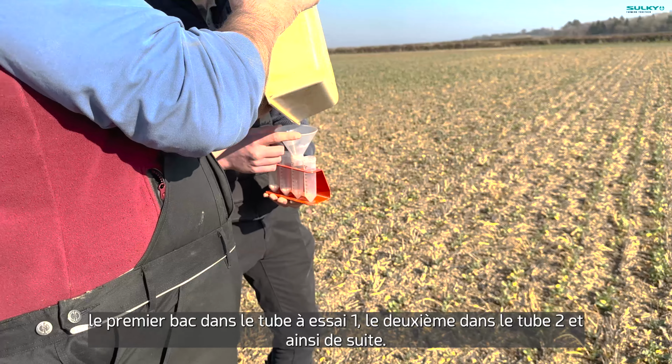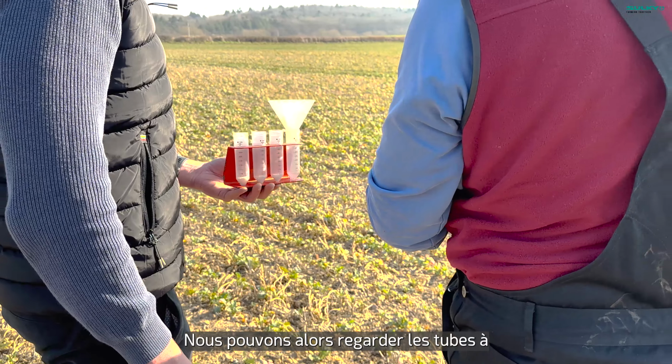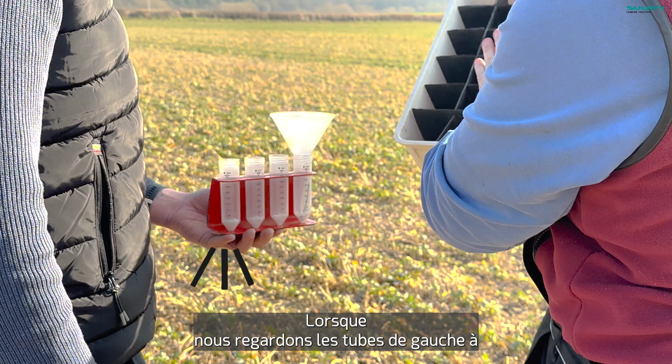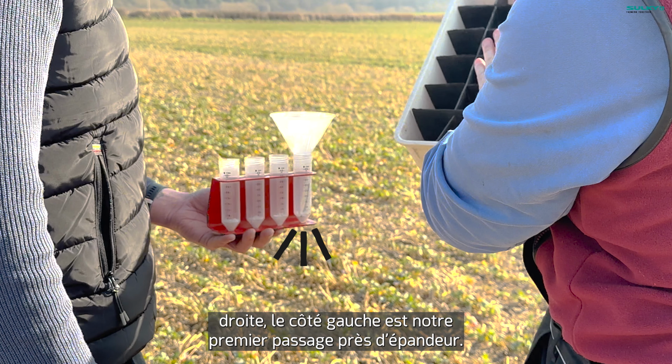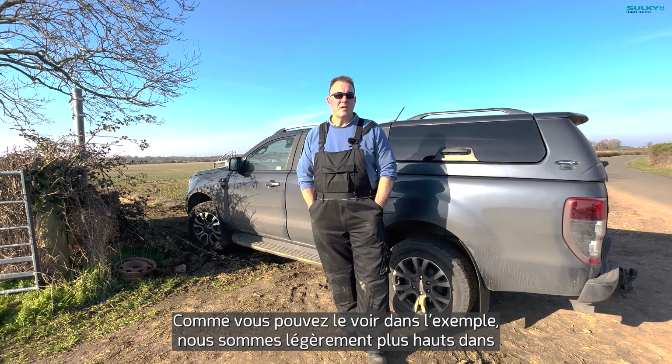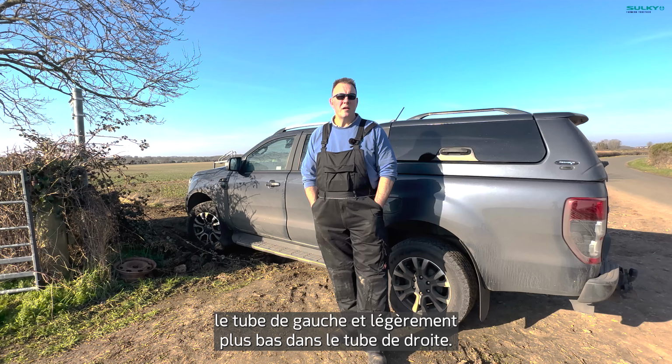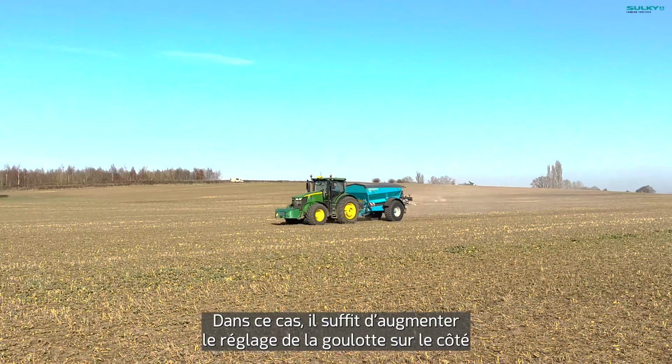When we look at the tubes left to right, the left hand side is our first pass nearest the tractor. As you can see in the example, we are slightly higher in the left hand tube and slightly lower in the right hand tube. So in this case we would simply increase the setting on the chute on the side to allow the fertiliser to spread farther.